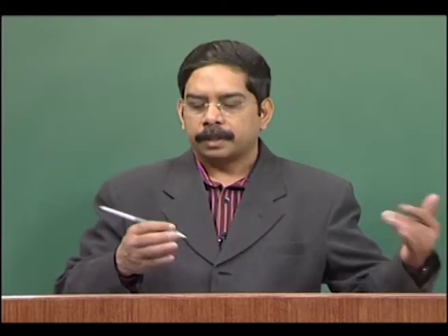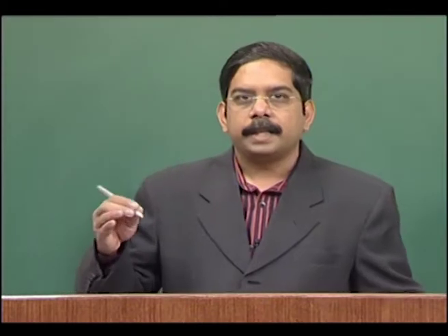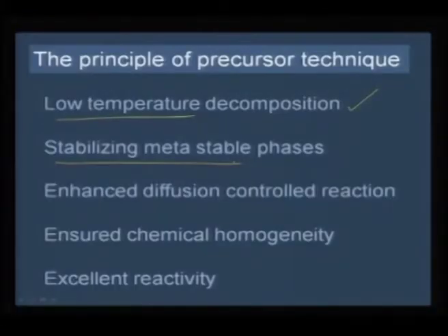What is not possible at high temperature may become possible at low temperature. So, you are essentially trying to see whether you can stabilize a metastable phase, which means a phase which is only stable at very high temperature and on cooling will revert back to a different phase, but because of this solid solution route you are stabilizing a metastable phase at room temperature.